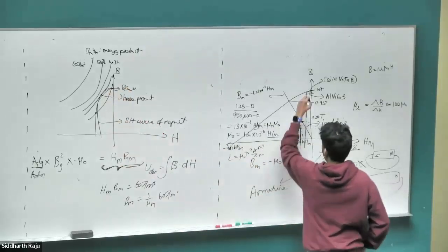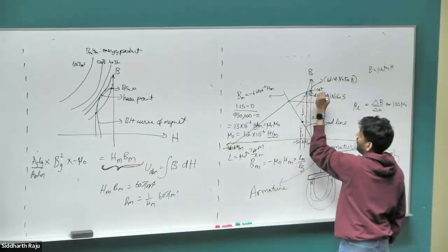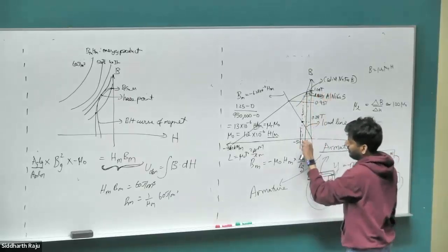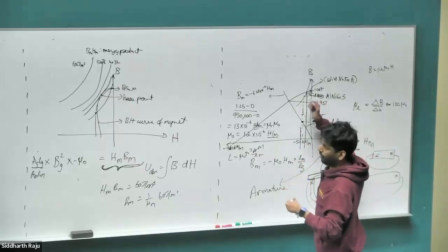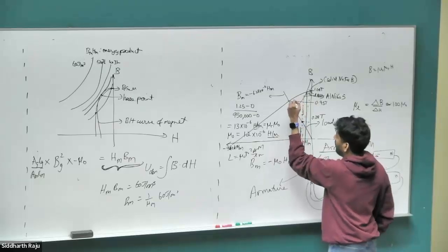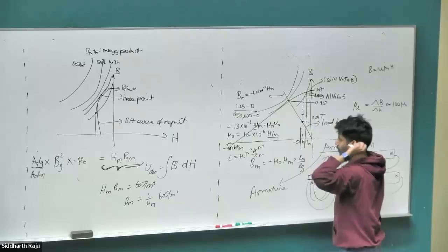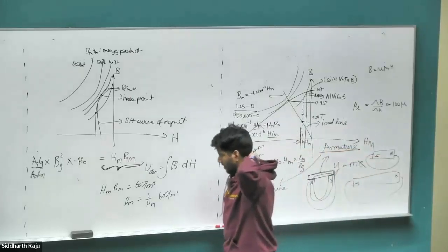For our Alnico, that value would be around 1.0 Tesla or 0.95 Tesla. But the problem is even the tiny amount of air gap will prevent us from going to that particular H field. In case of neodymium, you can get a sufficiently good air gap and still operate at a point where you can get the most optimal value out of the magnet, right?